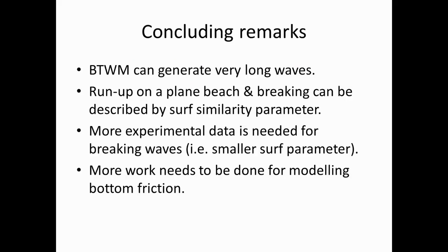So these are the concluding remarks. The new wave maker, the simple one, can make very long waves. And both run-up and breaking seem to be explained by a kind of surf similarity parameter, just like in regular waves and solitary waves. But I would need more data, possibly a much bigger wave tank, and also more work needs to be done for the friction factor.